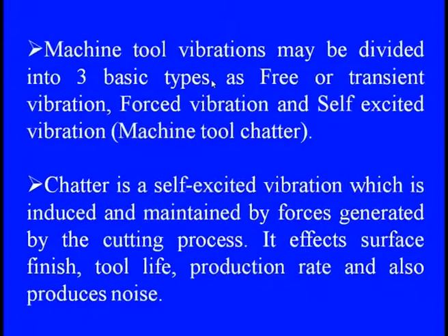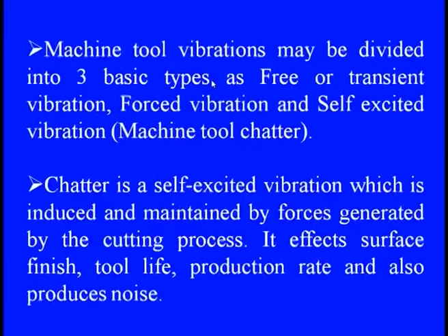And the self-excited vibrations can also be termed as machine tool chatter. So, chatter comes under the self-excited vibration, which is induced and also maintained by the forces generated during the cutting operations.